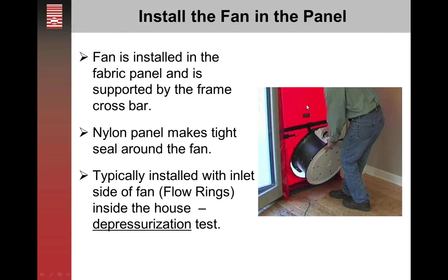Once the panel is in, we then install the fan, and the fan is held up on the crossbar. We want to make sure, again, that the nylon panel is nice and tight, and that we're installing the flow rings on the right side of the house. So if we're doing a depressurization test, that means we are going to suck air out of the house, then